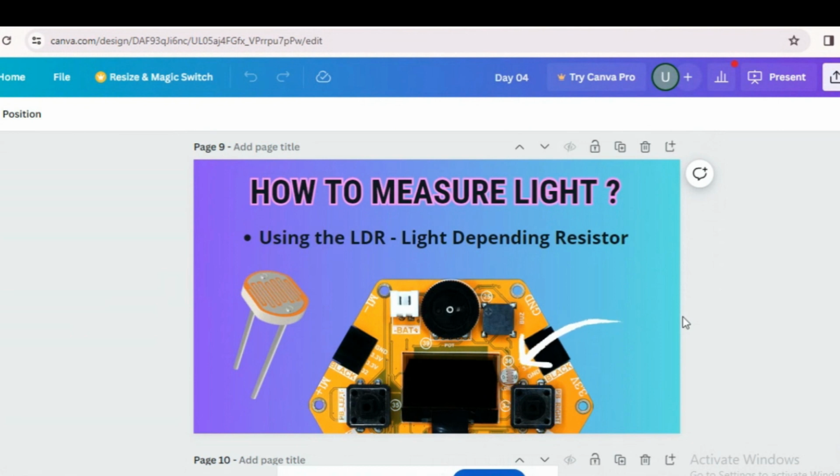Everything is dark. So we need to turn on the switches manually in order to light up the external lights. But here we are going to create a program using this Scratch language in the Magic Code. By using a sensor, it will detect the available light in the environment, and if the detected light level is less than some value, then it can decide it is night time or it is getting dark in the environment. So it can automatically switch on the lights. Right? So we are going to create such a program. That is what we call the night light. It will identify the night time using the sensor, and then it will automatically activate the light switches, right?